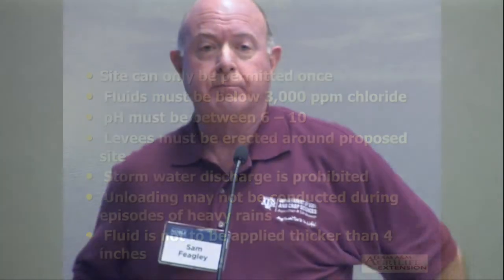Now, for most of y'all, you have probably watched materials grow before, and you planted seeds. Do you plant them 4 inches deep? If you do, do they ever come up? No. So 4 inches deep is way too deep. So we try to get them to apply no thicker than about 2, sometimes 3 inches, just depending on what that material might be. Most of our Bermuda grasses will come through 3 inches, but you put that fourth inch up there, and most of the time it's not going to come through, especially if it's a heavy clay, which is part of that material.